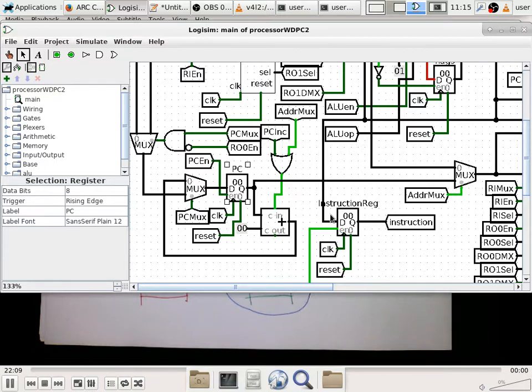Well, all you have to do is look up the microcode corresponding to LDAD, right? And then you look at how it exercises the multiplexers and demultiplexers to establish the path between RAM and register A. That is the whole reason why we use a toy processor, because this explains how opcodes execute much better than I can possibly explain, because this is the actual mechanism.